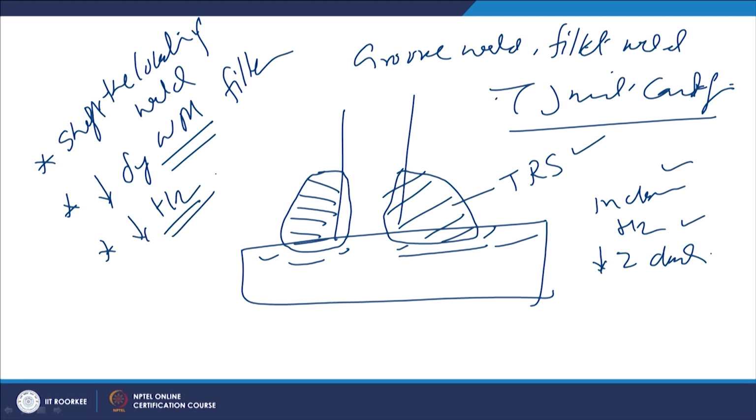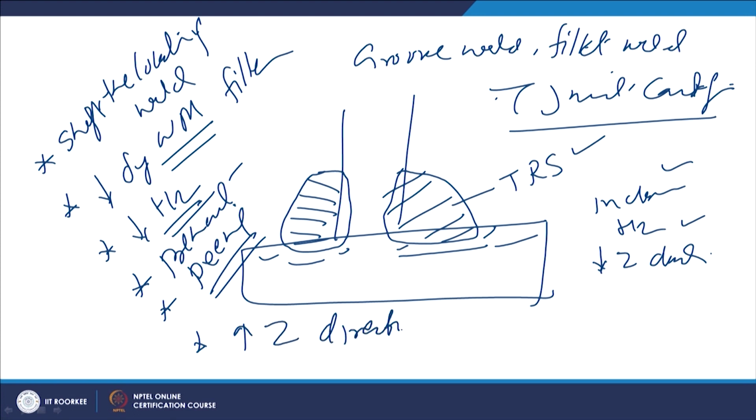This can be done through the use of low hydrogen consumables or proper precautions during welding, so that the entry of hydrogen in the weld metal can be reduced. Use suitable preheat, so that the reduced cooling rate and increased high temperature retention period help in the escape of hydrogen from the weld as well as the heat affected zone. Shot peening will help in releasing the residual stresses being developed, and then use base metal having high Z direction ductility.